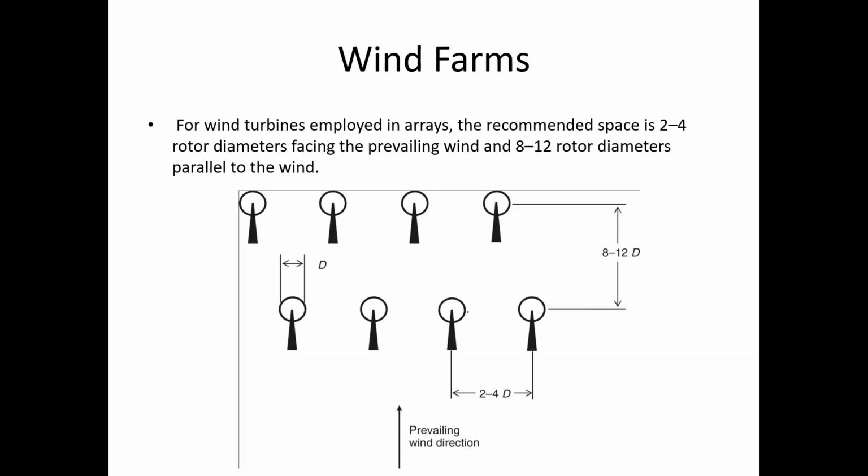One other thing I want to cover is just the concept of a wind farm. Now, you have a homework problem on this. So wind farms are just basically an area of land, a plot of land that has wind turbines spread out across it. When sizing a wind farm, it's important to know that you have to have a certain amount of spacing in between the wind turbines. If they're too close, the wind speed reduction from one wind turbine would affect the performance of another.